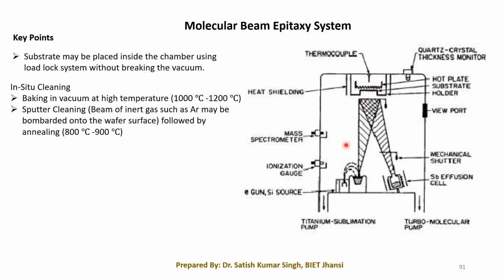So how can it be done in the case of silicon, as in this most simplified picture of our MBE system? We have to start the electron gun. Before that, we have to load this crucible with the charges, a particular charge, like in this case silicon. Then a particular dopant material has to be placed within these effusion cells, which are also known as Knudsen cells. So in these cells we have to place a particular material.